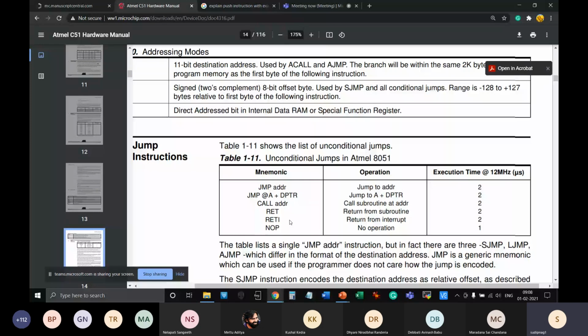There's a lot of automation which goes on in the background by the timing and control unit. So an interrupt can come anytime, whether it is hardware or software. You may not have the call instruction at that time, so the timing and control will automatically invoke two push instructions for saving the program counter for the return location.